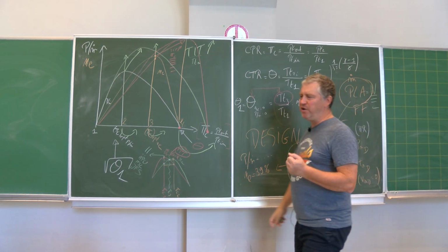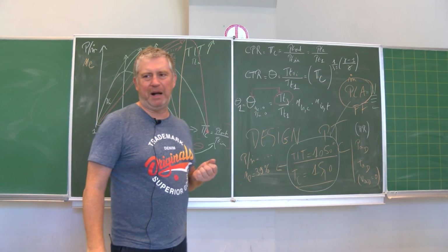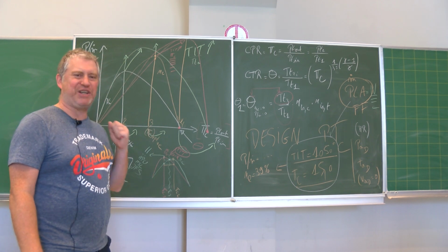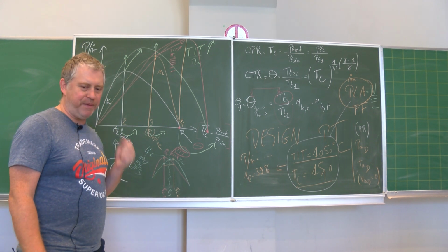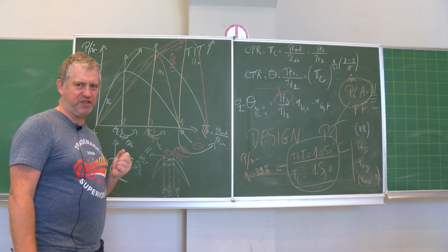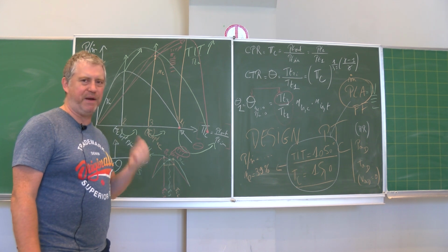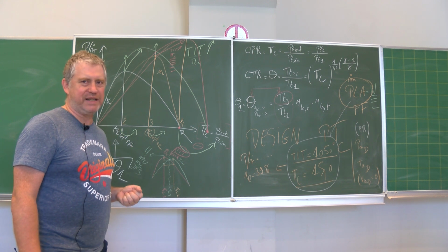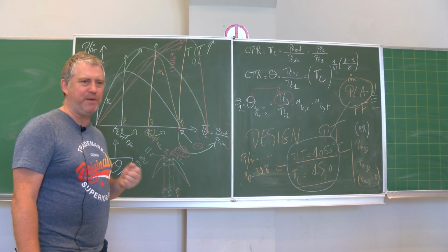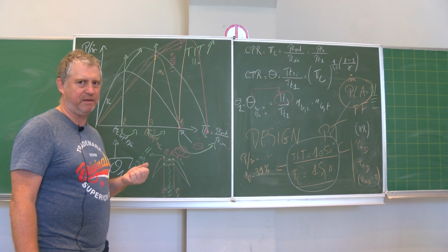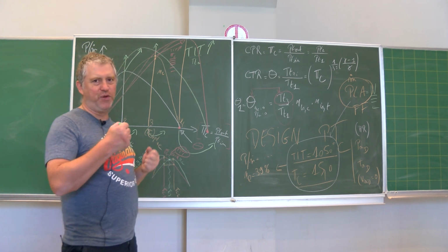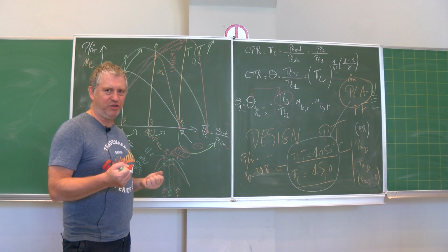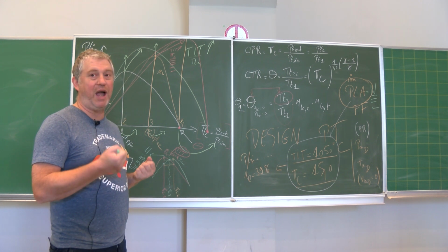Why? Because the rotational speed is a parameter that is very easy to measure. It's very easy to measure the rotational speed of a shaft. Very low cost, very easy, and the sensor reacts very quickly when you change the rotational speed. Whereas when you change the fuel flow, it's more difficult to measure. It's more difficult to measure a m dot.